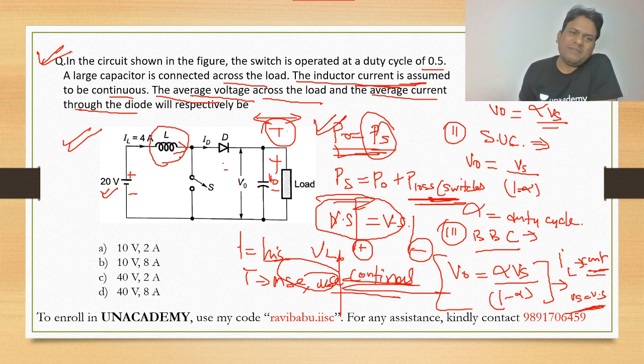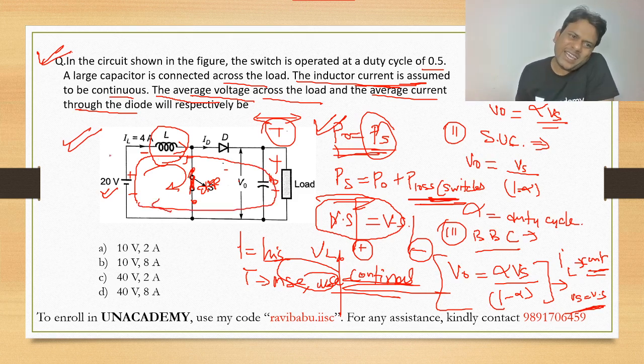The moment at which this switch is on, this inductor will get charged, but when this switch is off, this inductor will change its own polarity and will work as a source, so power will flow in such a fashion. In the second case, that means when the chopper or main device is off, this diode is naturally on because of the changing polarity of the inductor voltage.